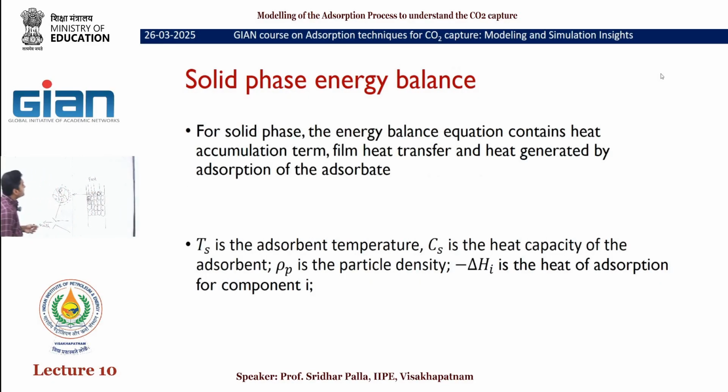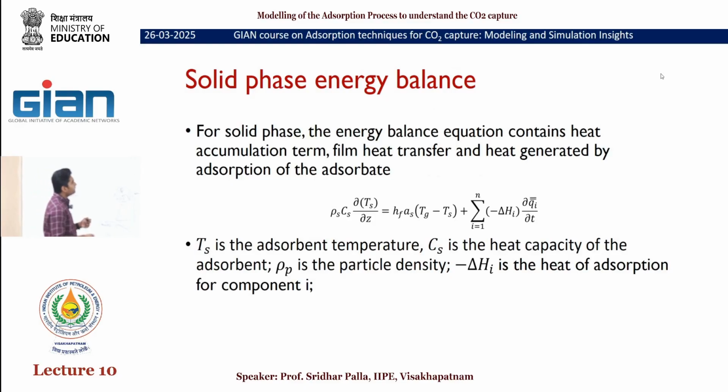Now coming to the solid phase energy balance equation, this is for the adsorbent. How the temperature of the adsorbent is changing with respect to the axial direction, and how the temperature changes from the gas to the surface of the adsorbent. And what is this last term? That is a very important term. If we remove that term, we don't get accurate results.